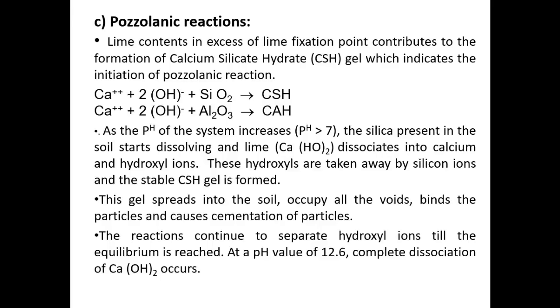Lime content more than the lime fixation point contributes to the development of calcium silicate hydrate gel, which is a natural tobermorite gel. This indicates the initiation of pozzolanic reactions.